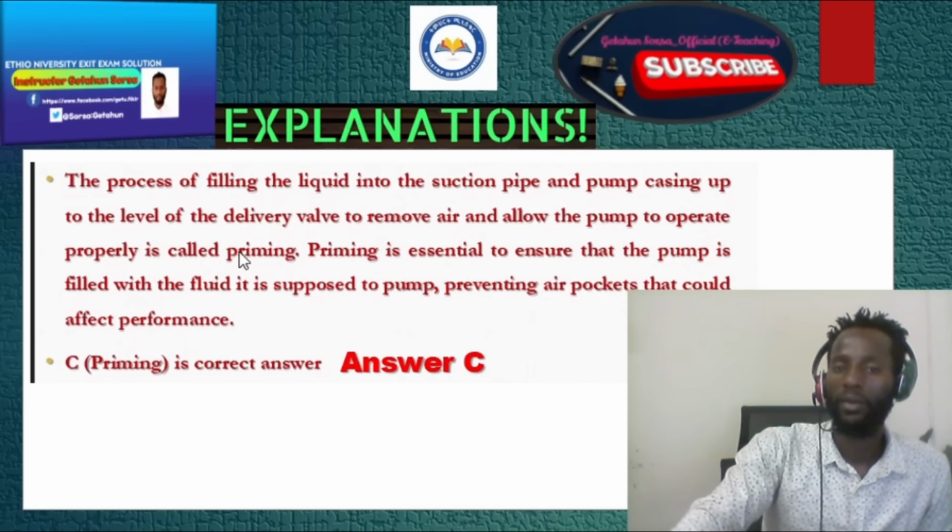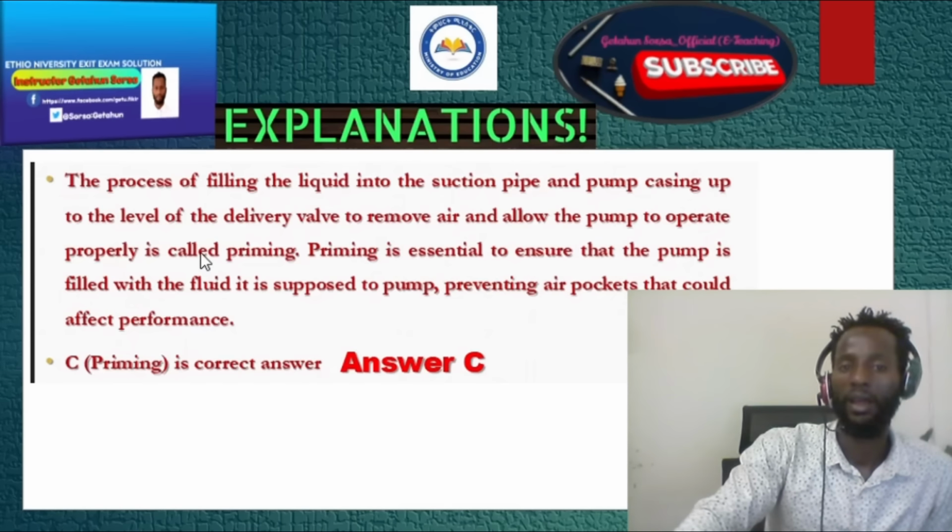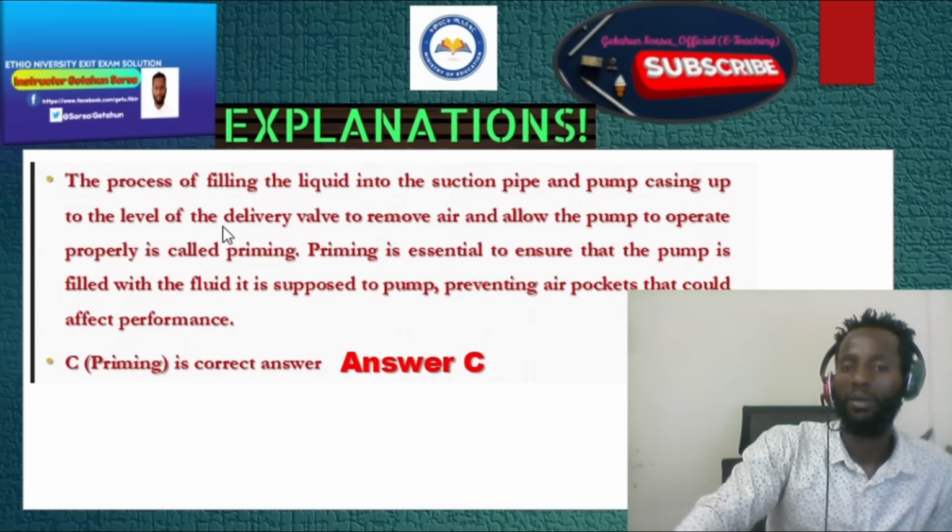When we fill the liquid into the suction pipe and the pump casing up to the level of the delivery valve to remove air and allow the pump to operate properly, we call it priming.